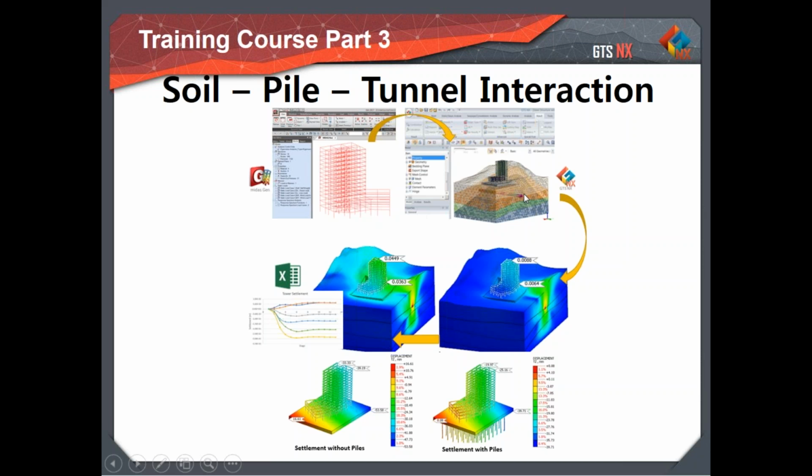In this case, the tunnel won't be the same 3D tunnel that we did. We want to show the versatility, and the program also allows you to model tunnels as 2D shell elements, which can be handy in some respects in terms of some of the results you can see. So we'll be modeling the tunnel, and in this case, we're actually going to see the excavation stages. We're going to excavate the tunnel in 5 sequences.